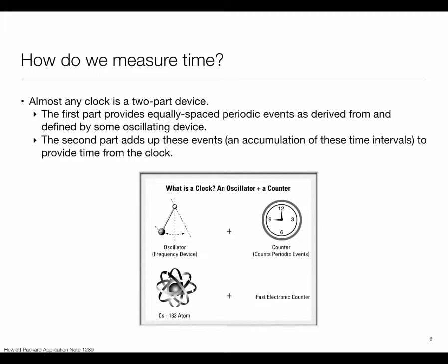If you think about a clock, fundamentally, deep down, there are two parts to a clock. One is some sort of an oscillator, and the other is some sort of a counter. Oscillators provide us the frequency, and the counter is where you have some representation of the time, and then you'll have some sort of implied mapping function which takes whatever the counter shows and maps it into some agreed-upon notion of time.